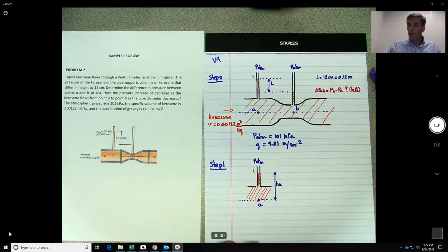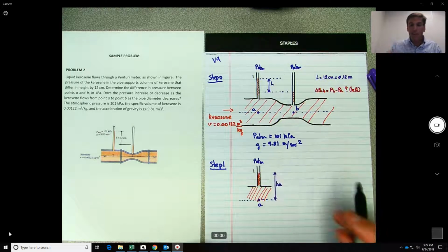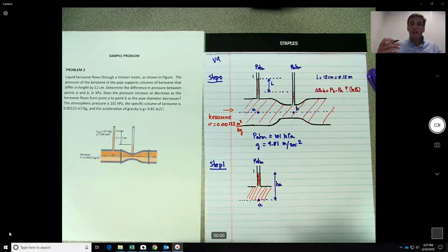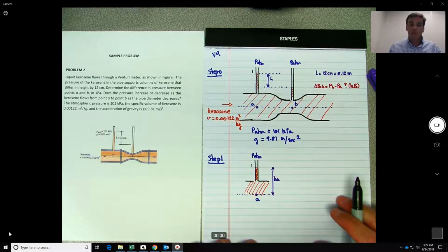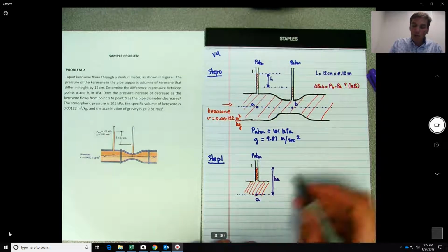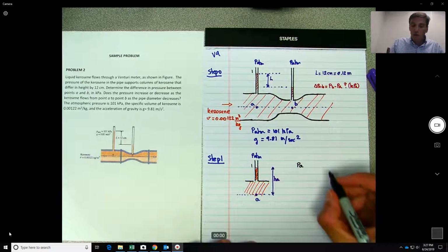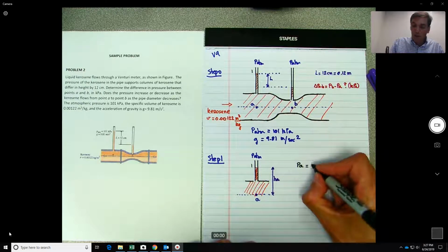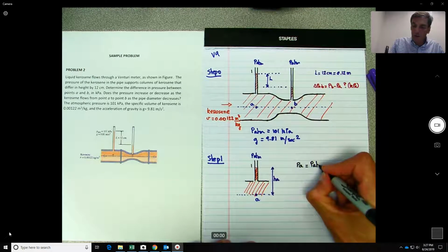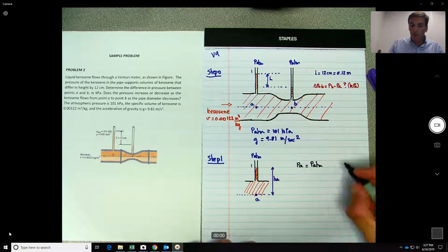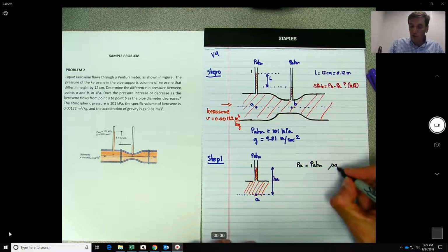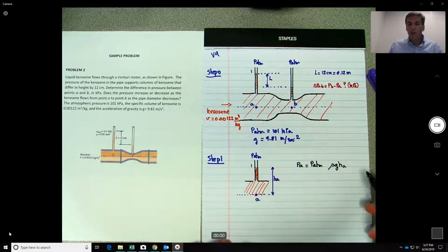Okay, so over here, just by looking at this equation, again, we could take one little element and do the summation of forces, but let's follow the procedure we did for the manometer. So what should be the pressure at point A? So we know it should be equal to the P atmosphere, and then either plus or minus rho G H, and in this case would be H sub A. So where is the pressure higher?